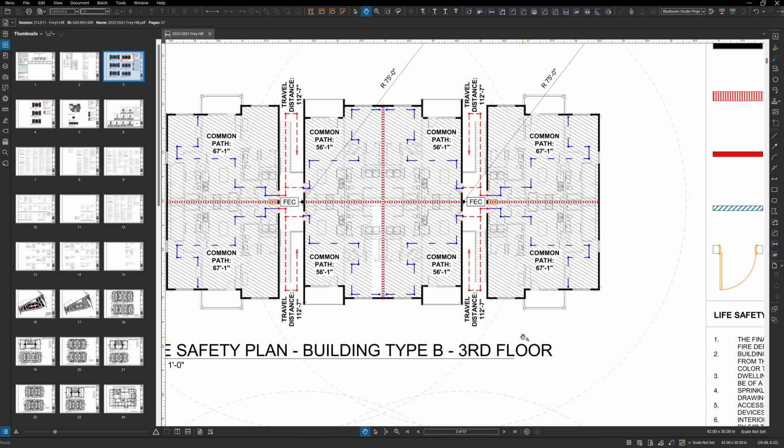And even from there, some people want to see a fire partition where it's rated from both sides, where some folks want to see it where it's rated from the inside only. The key factor here, the thing that's super important, is whatever we say in the life safety plans, whatever we define it as. And this particular individual is defining it as U356 rated from inside only.